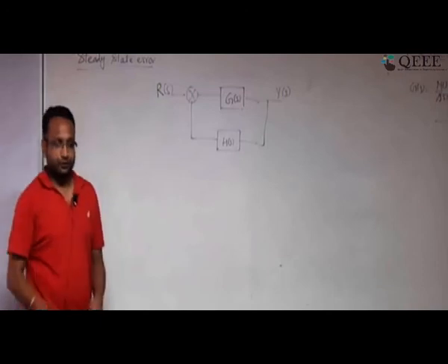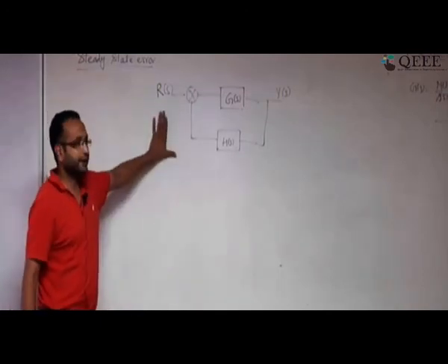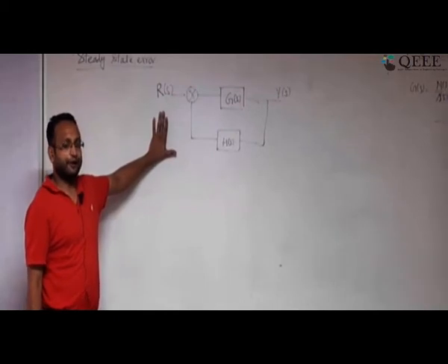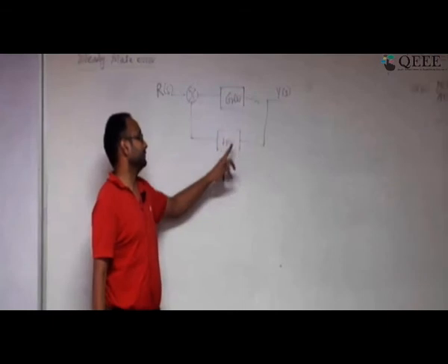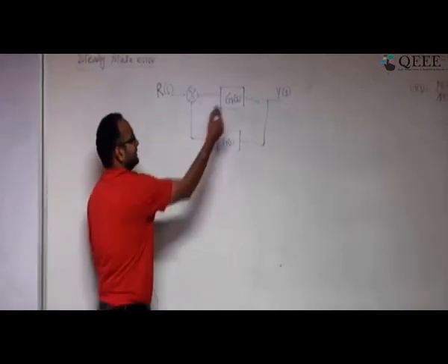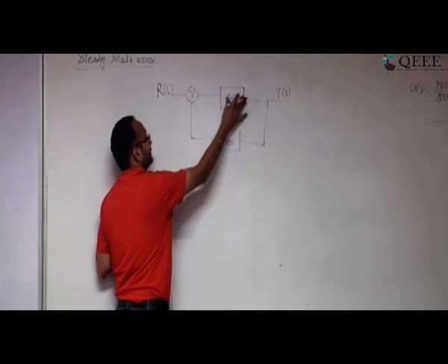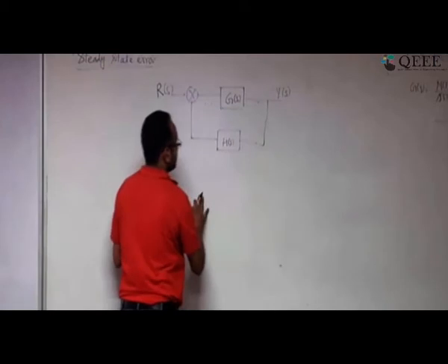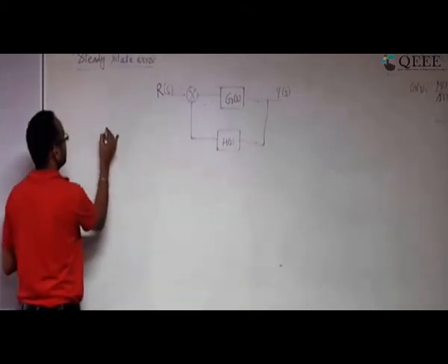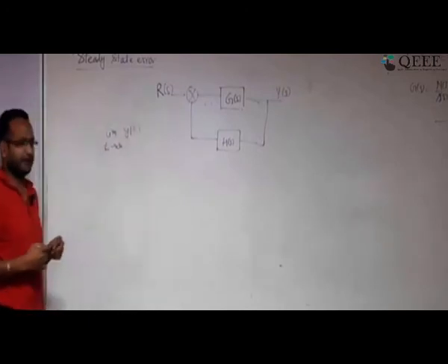Okay. So as I mentioned earlier, this is going to be a typical block diagram of a closed loop control system, correct? This is the plant, this is going to be H of S, and I am just mixing your controller, actuator, everything in one. So as I mentioned, how do we define the steady state value? It is the limit t tends to infinity of y(t) that we say is the steady state value.